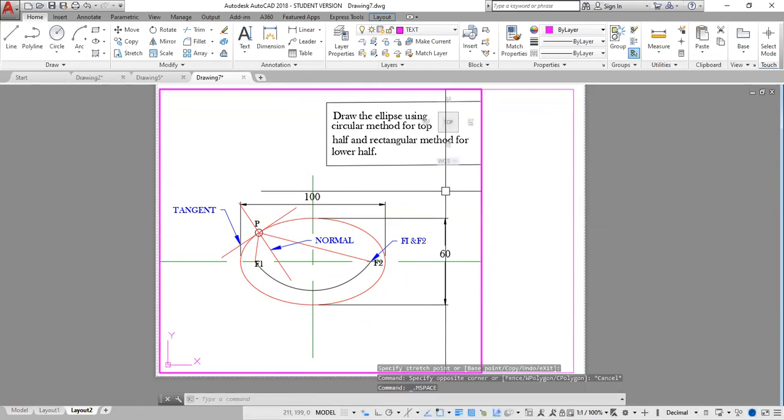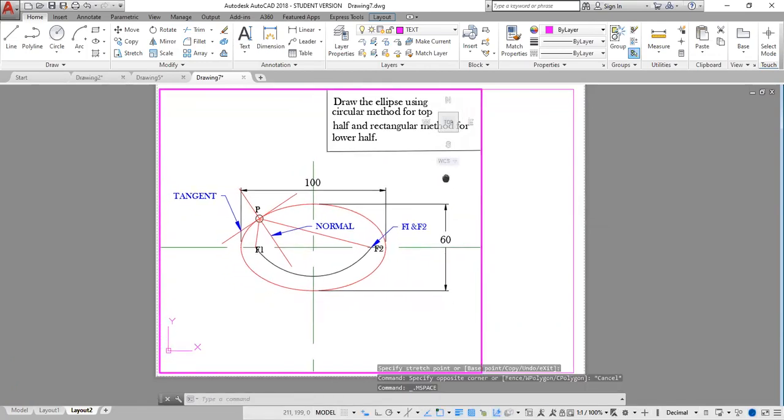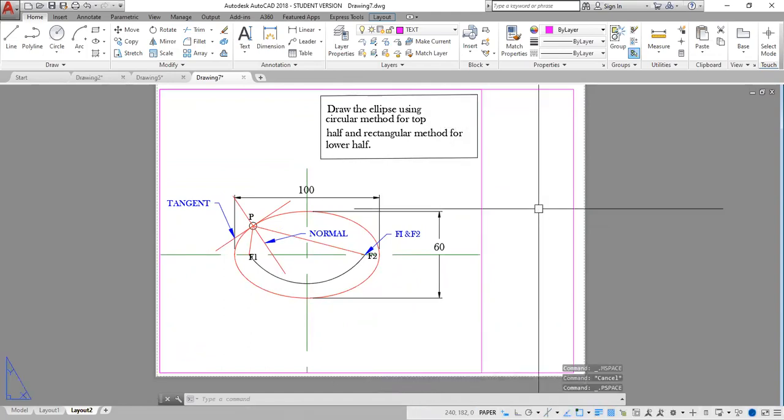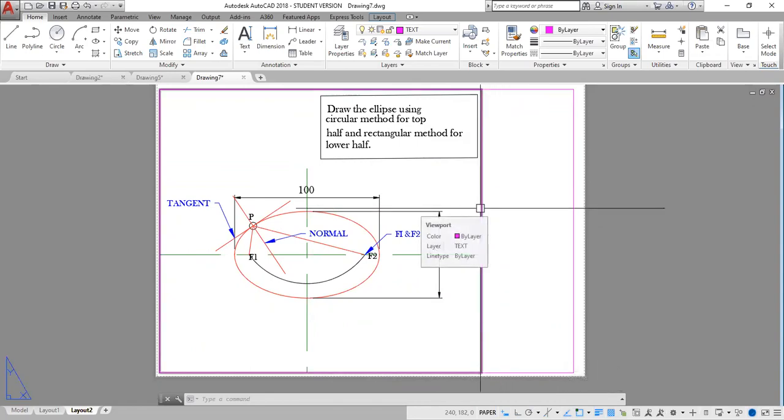We could probably adjust this. Click 2 times inside here to adjust this to fit onto the paper. And that seems good. Escape. Click 2 times outside to accept this. It's best to have a separate viewport layer. With a separate viewport layer, what we can do,